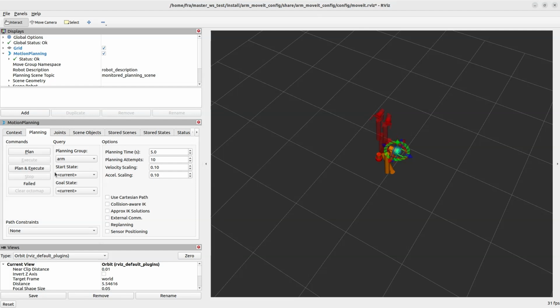The main problem of the MoveIt2 wizard, and in particular the demo launch file, is that in ROS1, under the hood, all the fake controllers were spawned. Then you can simulate your robots and your trajectory even if you didn't have any controller, because by default the fake controller was loaded.